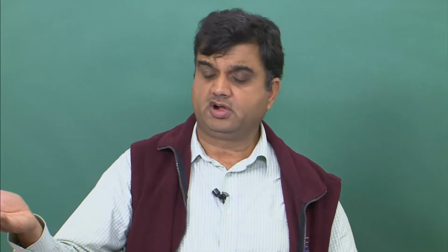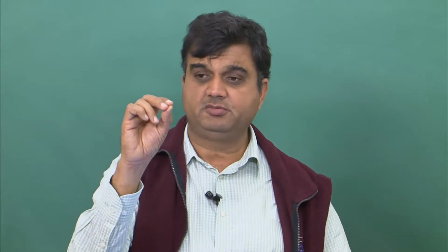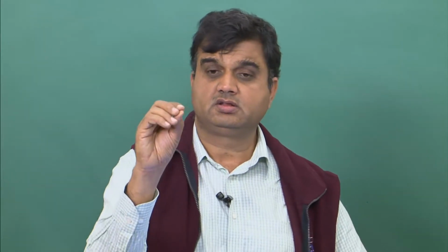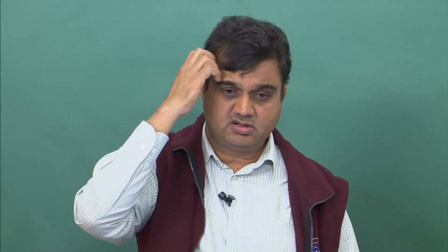So if I have a 1000 hertz wave, its wavelength will be 340 meters per second divided by 1000, so it will be 34 centimeters. If I have an object, let's say 5 millimeters in diameter in this noise field, then 5 millimeters is extremely small compared to 34 centimeters, the wavelength of the sound at 1 kilohertz.